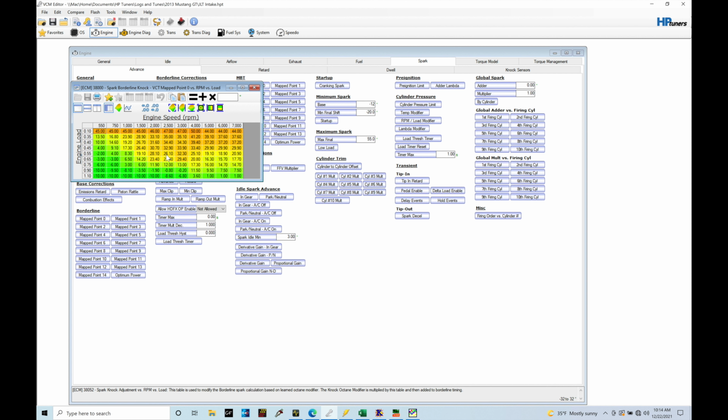So we'll find in the Otto cycle, we actually have 720 degrees of engine rotation to complete one Otto cycle. So we'll have 4 different strokes of the Otto cycle. We have our intake stroke, we have our compression stroke, we have our power stroke, and we have our exhaust stroke. So we have the 4 strokes that make up the Otto cycle, and it has to go through all 4 strokes in order to complete that process.